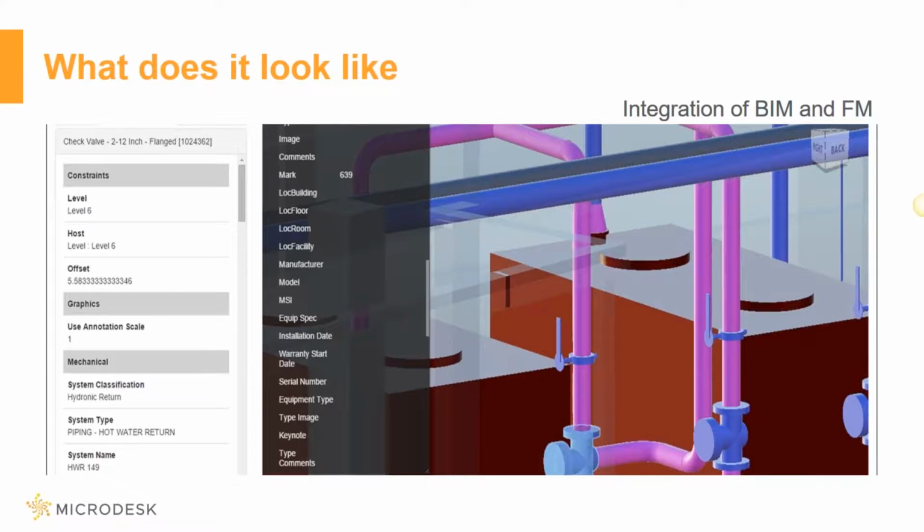Way too often, depending on if you have a campus, for example, traveling to an area where something needs to be repaired and back again, you might spend 2 hours just going back and forth, trying to find out what the right piece of equipment is. Or trying to identify, do I need a ladder? Do I need a 12-foot ladder with me, or is a 6-foot ladder okay? Again, the Revit model, the BIM model, can give us all that information, and we can very easily make it available to the operations staff in this lightweight format.